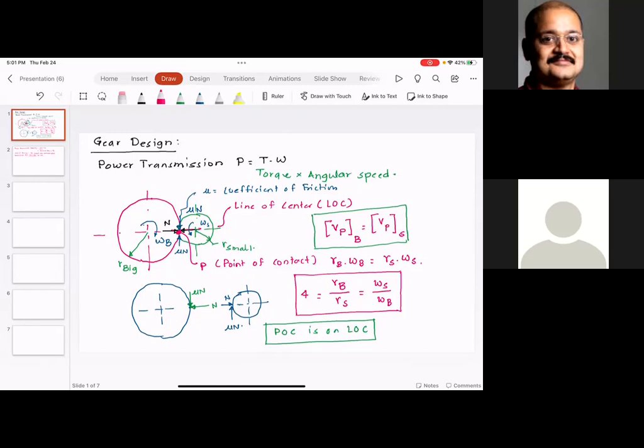Chain drives are. So in chain drives, what you have is sprockets. And because of that, you ensure that if you are applying torque at the pedal, some torque, depending upon the design, will be applied at the wheel. So chain drives are positive power transmission elements.